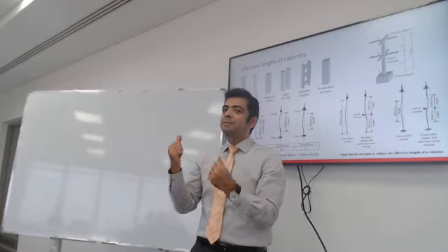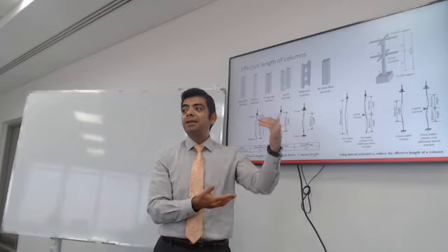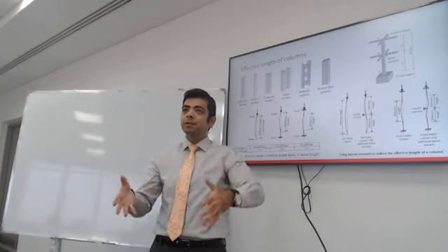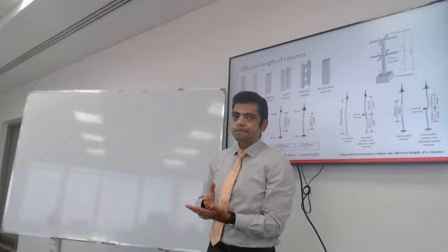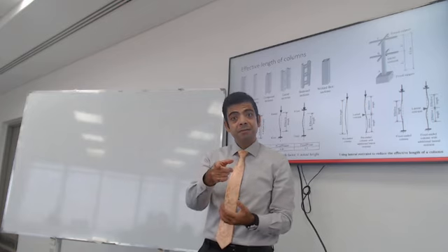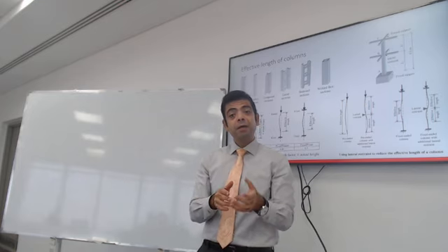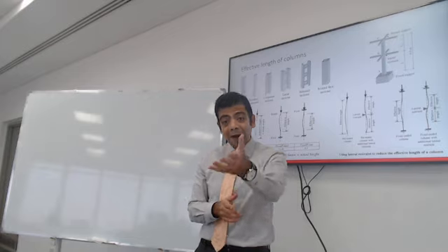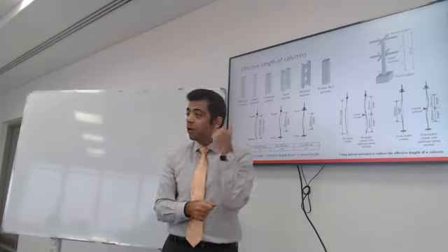You know if it's fixed or pinned. How do you get the effective length of a column in a building like this? I consider the height of each floor. Yes. How do you get the height of each floor? From the architecture design, the architecture drawing. So you pick up the phone, call the architect.